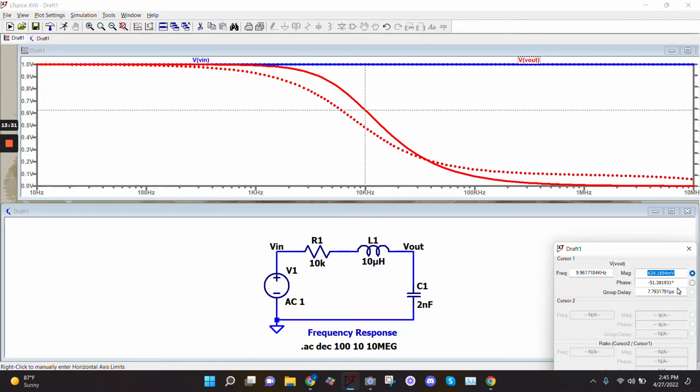Okay, so this is basically a way of looking at how an AC circuit behaves, instead of at one frequency, over all of the frequencies, because this is really important. When we use these AC circuits, we use them for filters. Basically, a filter is a circuit that will allow certain frequencies to pass through it and not allow other frequencies to pass through it. And so this circuit right here would allow all of these frequencies to pass through to the output, because basically my input and my output are the same. That's a filter. It lets those through. But way out here at these high frequencies, it doesn't allow the signal through. It's doing what's called attenuating. It's basically knocking the amplitude way down. So this is why this is important.